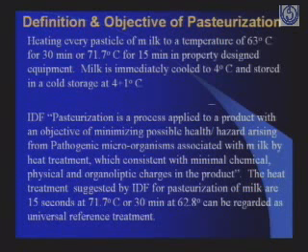The definition of pasteurization as per the PFA is heating every particle of milk to a temperature of either 63 degrees centigrade for 30 minutes or 71.7 degrees centigrade for 15 minutes in properly designed equipment. Milk is immediately cooled to 4 degrees centigrade or below and stored in a cold storage at 4 plus minus 1 degree centigrade, so that once the pathogens are destroyed, the other microbes in milk should not multiply in number.